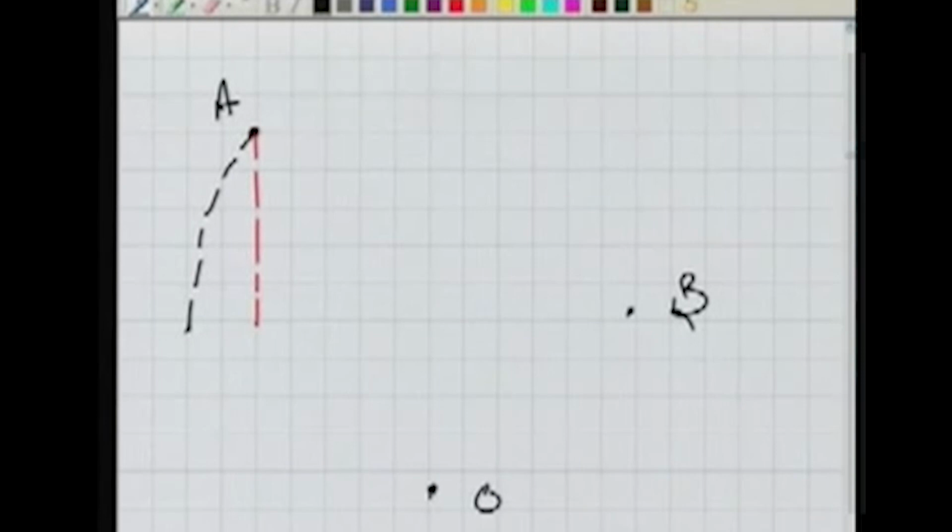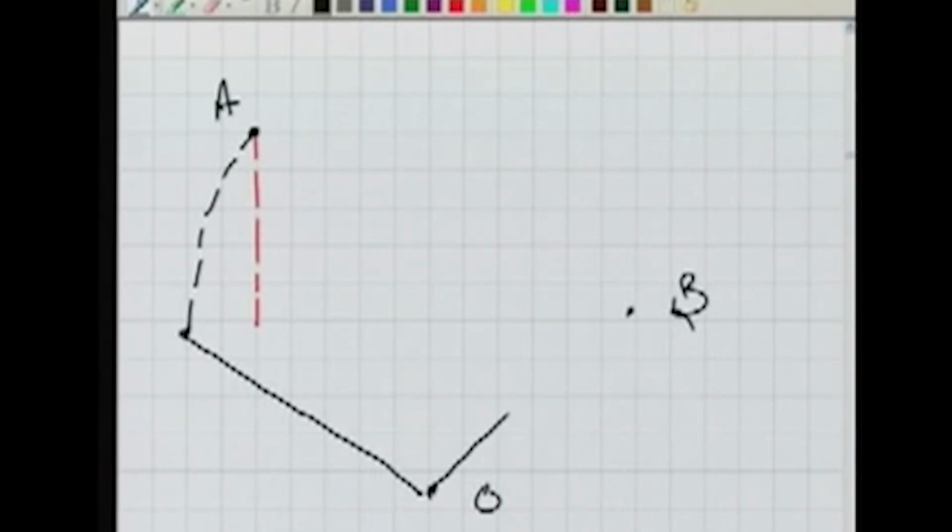Then, starting from this point, I rotate my line of sight, or my telescope, so as to reach B. I bisect B and measure the angle, let us say alpha plus some error, because alpha is for the actual line of sight, if there is no error.